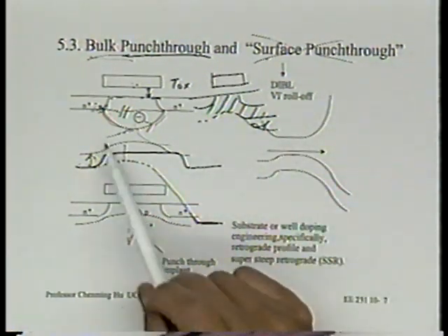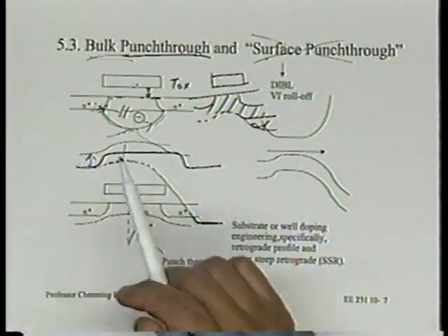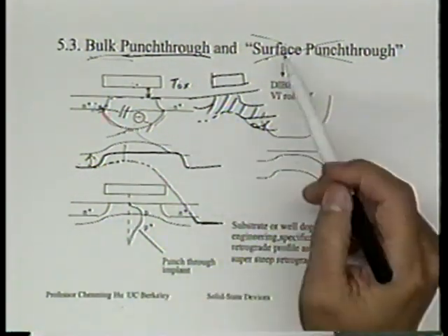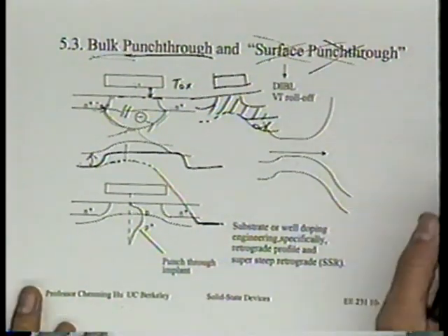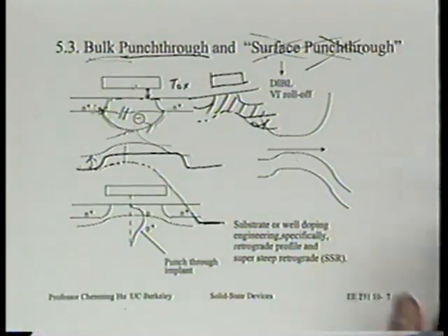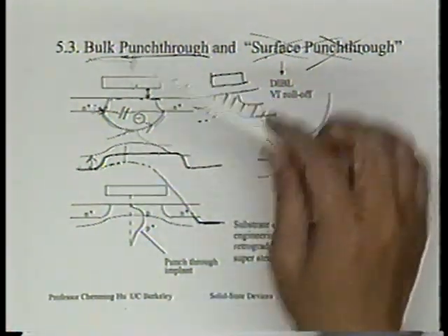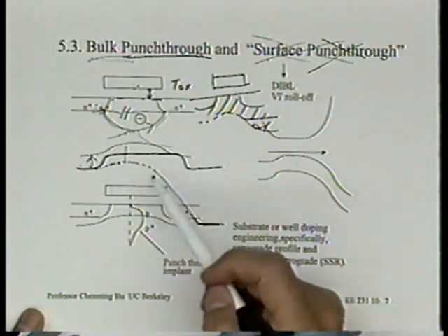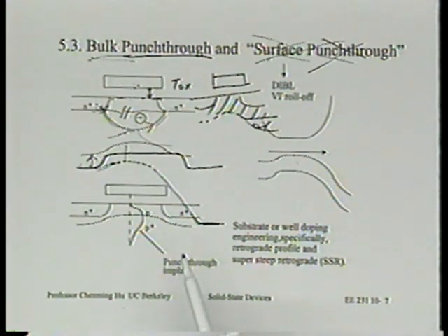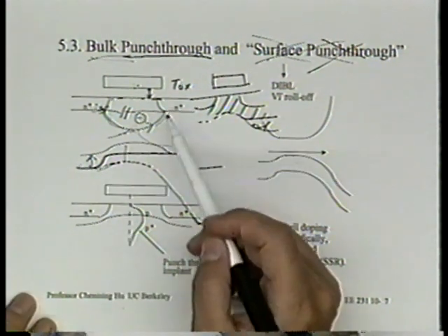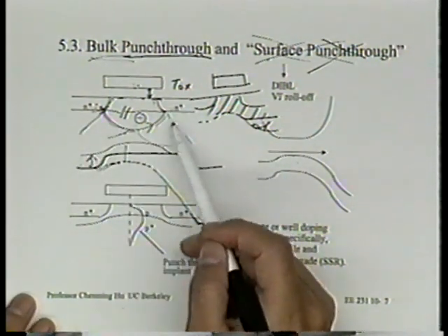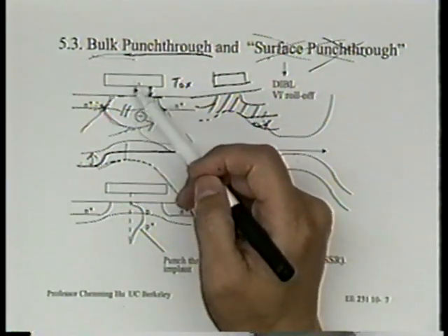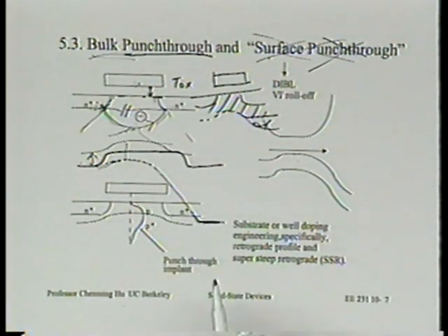The good picture is the barrier. You have to think about a barrier, right? When a barrier becomes low, you're going to get punched through, right? All right. So let's not use the terminology surface punch-through. What controls surface potential is what we talked about last hour. What controls the bulk is a very similar concept, except we don't have that p-n junction, the oxide's boundary. And in fact, this picture, this energy band diagram, is easier to solve. If you ask me how to solve this, I would approximate it as two almost parallel plates, N-plus P N-plus junction. Just solve that. And the third boundary, which is the gate, because it's so far away, is not so important, right?